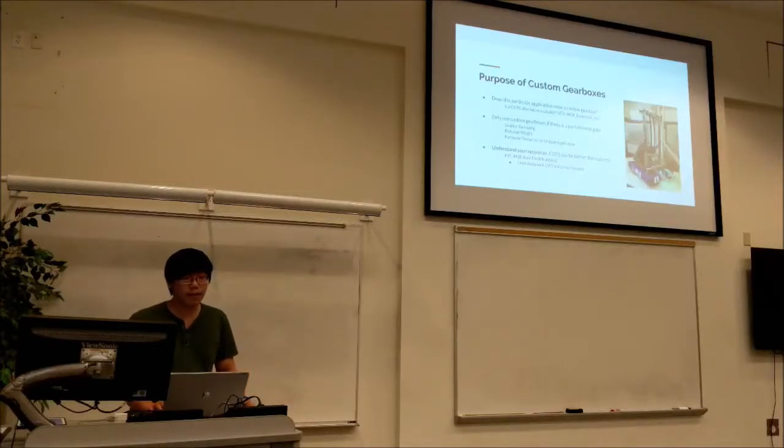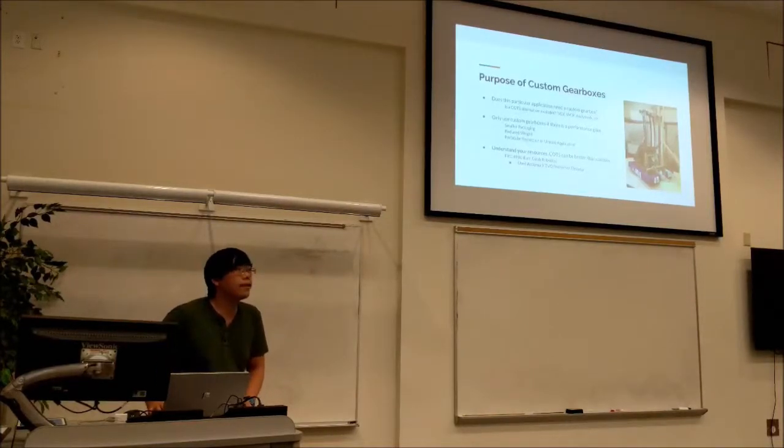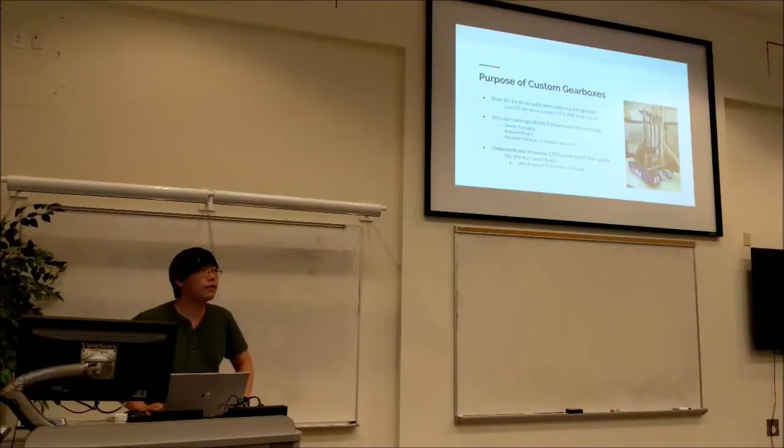So you really only want to design a custom gearbox if you can have some sort of performance gain, whether it's smaller packaging or reduced weight, or there's just a particular feature of that application. And it's also important to understand your resources, because most teams have limited manufacturing resources, and you don't want to waste that on a custom gearbox if there is a COTS alternative available.